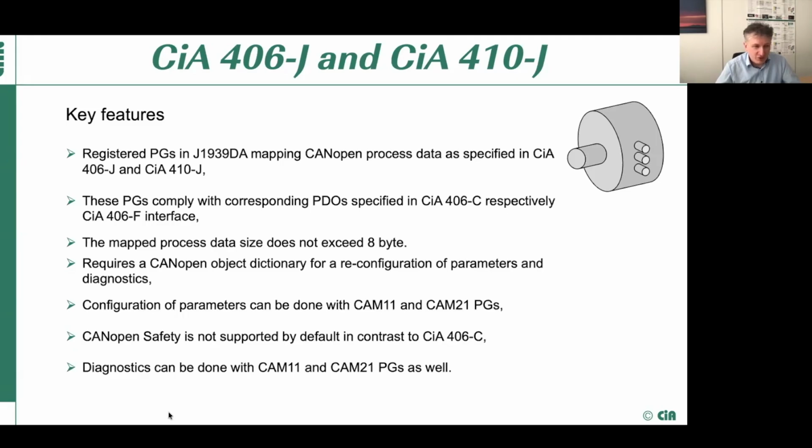The only thing I've mentioned here: CanOpen safety is supported, a special way of machinery functional safety that we standardized, which we have applied for our CanOpen version of 406. Of course, J1939 has its own safety, and CanOpen safety is not mirrored in there. It is not supported in this case. The inclinometer and encoder just provide their necessary process value.